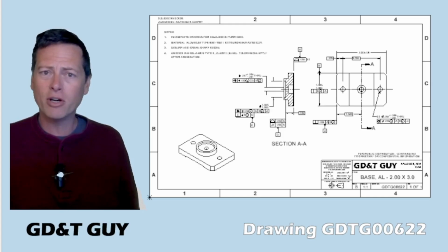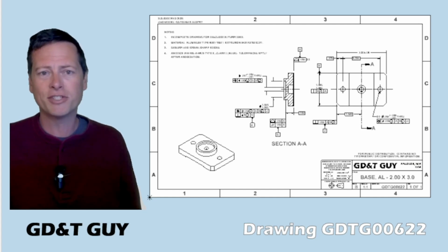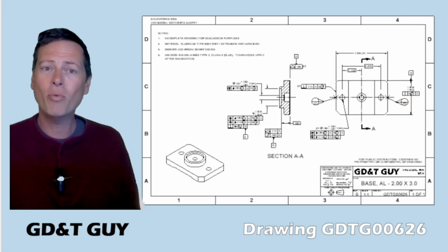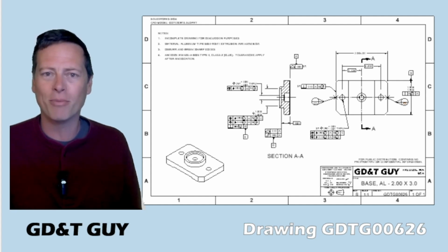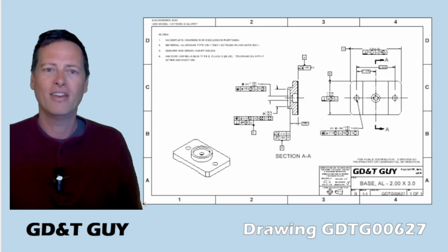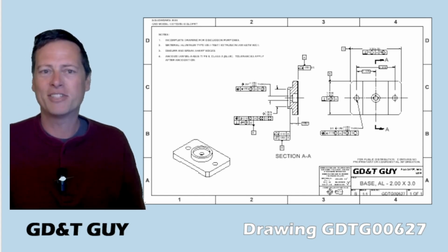So we will look at several approaches to establishing that tertiary constraint off the 3-inch width, starting with the simple, all the way to the quite elaborate. And we'll see what these callouts really do, how accurately they define our functional requirements. Do they solve problems? Do they create new problems? And by the end of this, we'll see that at least one of these is actually pretty good. But I'm thinking still not great, especially if the geometry were any more complicated than this rectangle. But that's all going to be quite a bit later, towards the end of the episode.